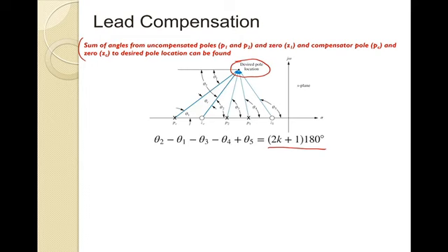So you can see, maybe I have two pole locations, P1 and P2, which are my uncompensated poles. I have my uncompensated zero, and then here are my compensator pole and zero, and you can see all the angles that we have here. What I'm showing is that with the compensator angle between the pole and zero, theta sub c right here, I can define my compensator zero.